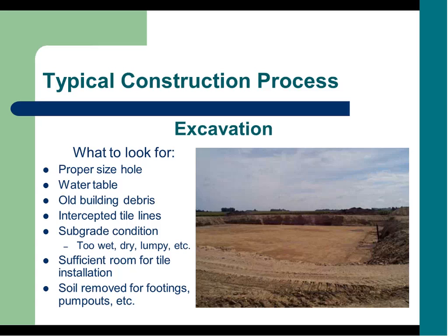Typical construction process, excavation and what to look for. Make sure the hole looks like it's the right size. I mean, you've got the plans with you. It's a judgment call as to whether it's looking like it's supposed to. Water table, old building debris, tile lines that they may not have known about that they cut into. Again, conditions, is it overly wet, is it overly dry? Have they not prepped the site properly where there's big chunks of something in the middle? Sufficient room for the tile and soil removal for the footings and pump outs.